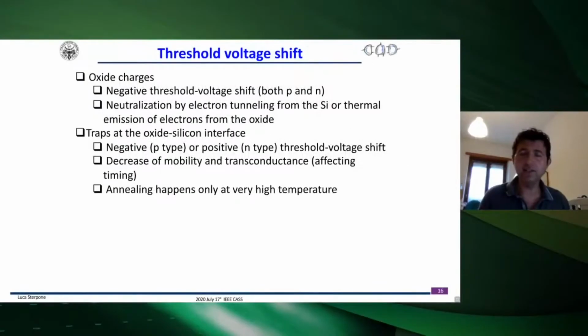On the other side, all the particle phenomena that I discussed will affect the signal propagation and characteristics inside your circuits. For example, if we think about a memory cell, a particle can cause a threshold voltage shift. It means that, for example, to change from 0 to 1, you may require less voltage because the threshold will change.